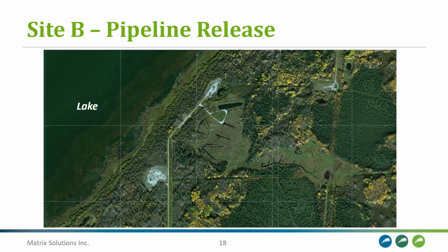Other remediation activities included installation of a series of containment berms and 1 to 1.5 meter deep trenches and boreholes to control and collect that surface water runoff before it reached the lake. And these are some of the linear features that you can see on the aerial photograph here.